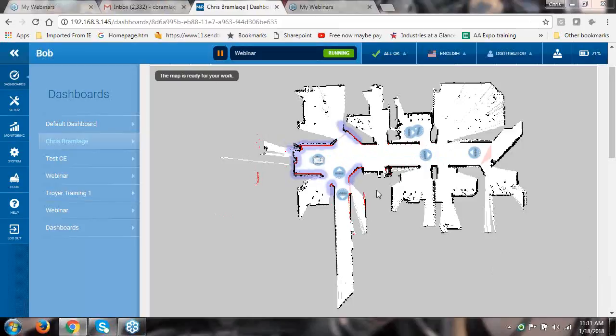Let me just describe how the joystick works. If you set it to fast speed, as you move it, it reacts pretty quickly to your commands. If you set it to a slow speed, it reacts pretty slowly. At any time when you're using it, the safety systems are still in place on the robot so that if it comes near an obstruction, it's going to go into an e-stop. That's a recoverable e-stop. It's not one where you have to interact with the robot to get it moving again. You can simply remove the obstruction or move the robot and it'll let itself run again. Thanks for the questions. And we'll get into users because that's a real key issue of this whole dashboard.